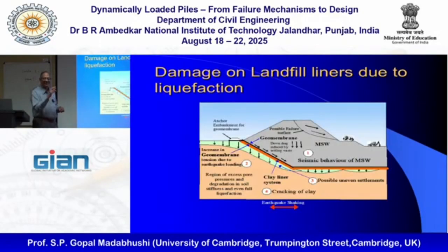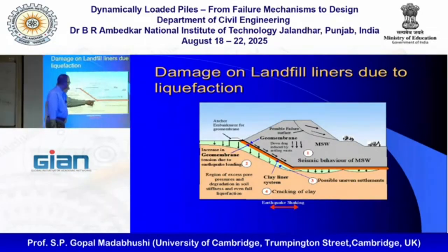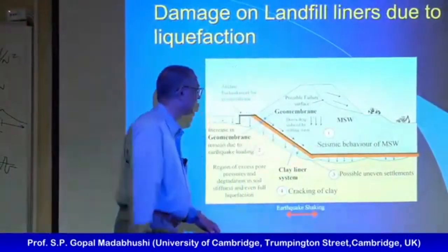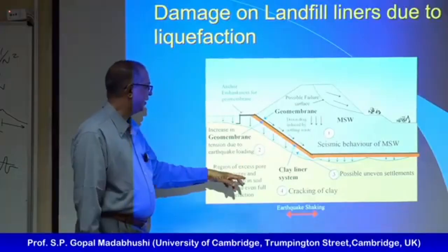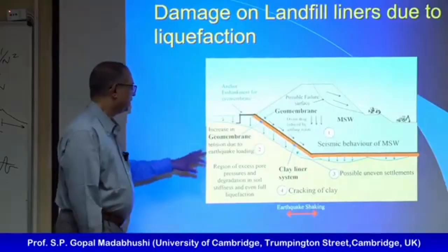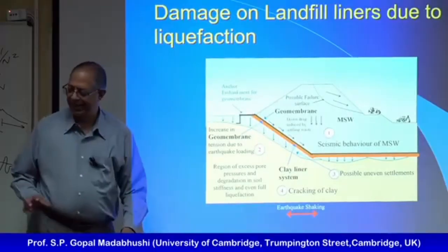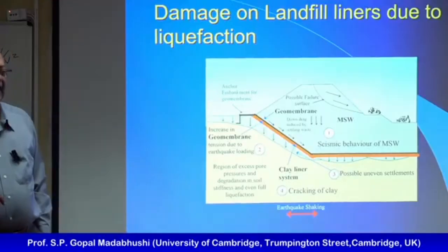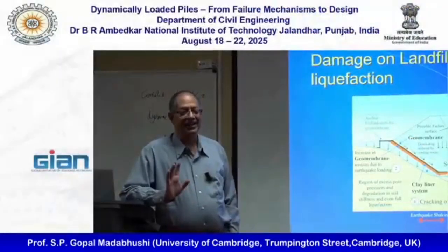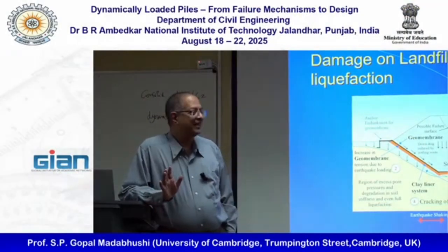We tried outside Delhi and elsewhere. A real, properly designed landfill should have a clay layer, a geomembrane, a base layer, a geomembrane, and it goes onto the other side as well, right? And after the waste is filled, you also have to put a top cover. Now these types of landfills have been built in Southern California since about the 1950s, okay?